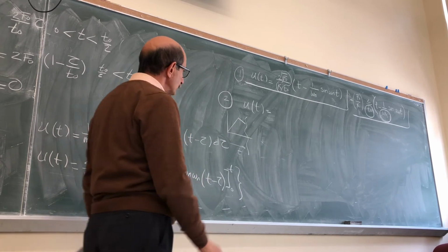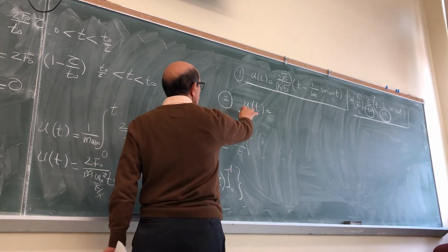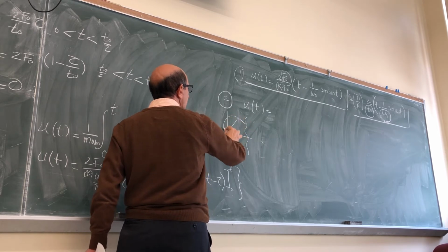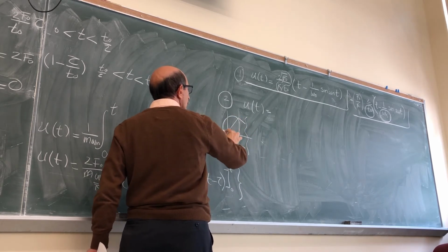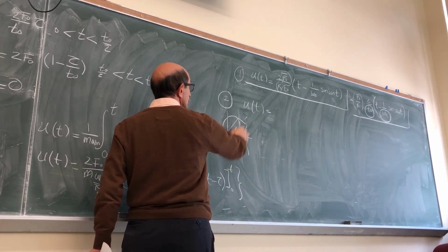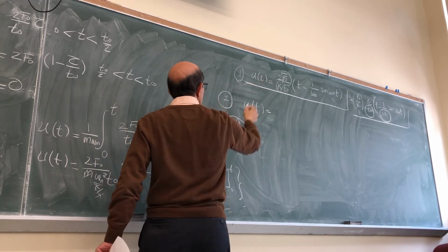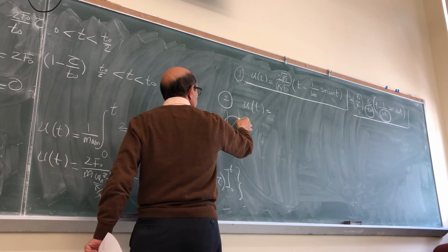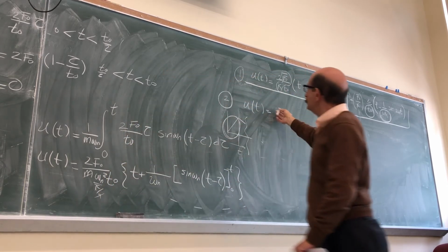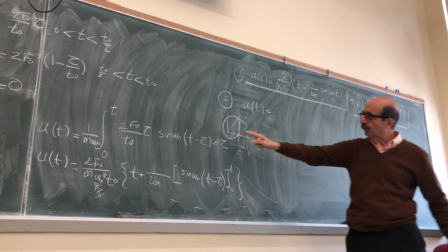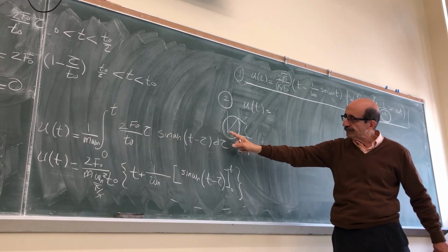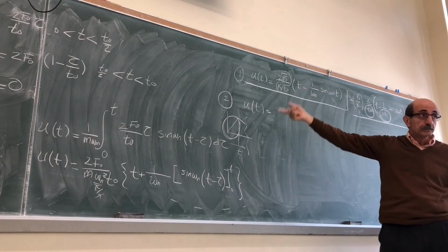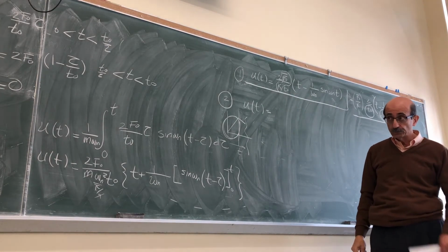So the response would be accumulation of the response that you have gained all the way from here to here, which is governed by that, plus the response from this point on. So you have two integrals, one for evaluating the response from here to here. Now you have the particular value of t being t0/2.